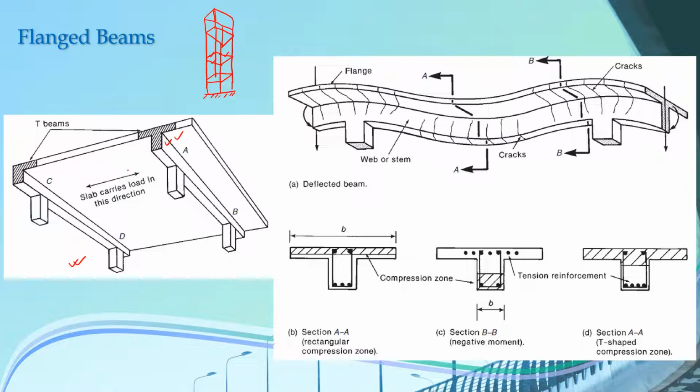this diagram shows a slab system which distributes the load that is coming onto it in only two directions, that is, in these two directions here. This type of slab is generally known as a one-way slab. We will discuss it during our design of slab lectures. But for now, just imagine that all of the load that is coming onto this slab is distributed in these two directions, and those loads finally reach the longitudinal beams that you can see in this diagram here. So the loads that are distributed by this slab are resisted by these longitudinal beams here.